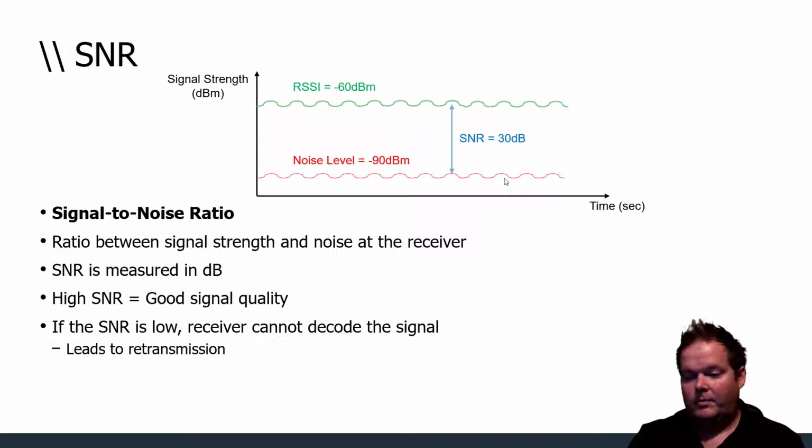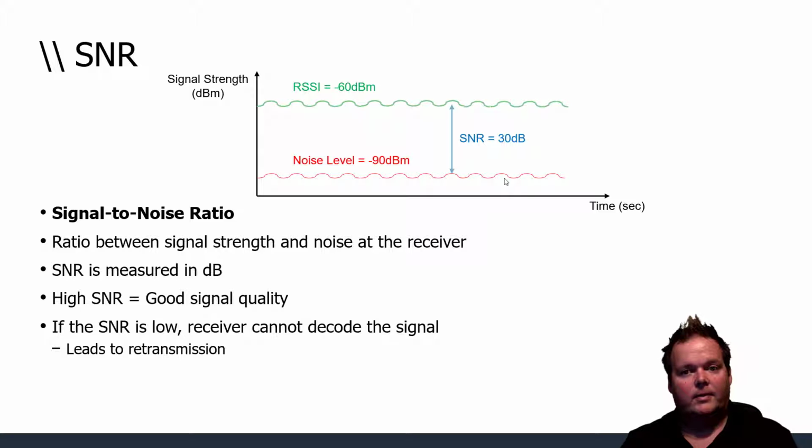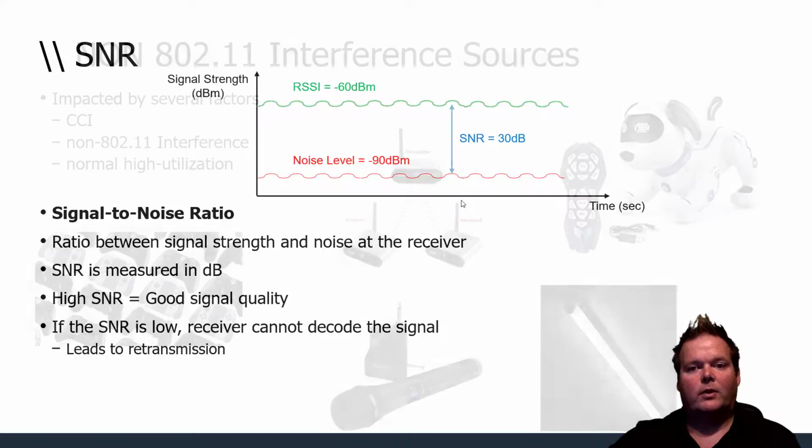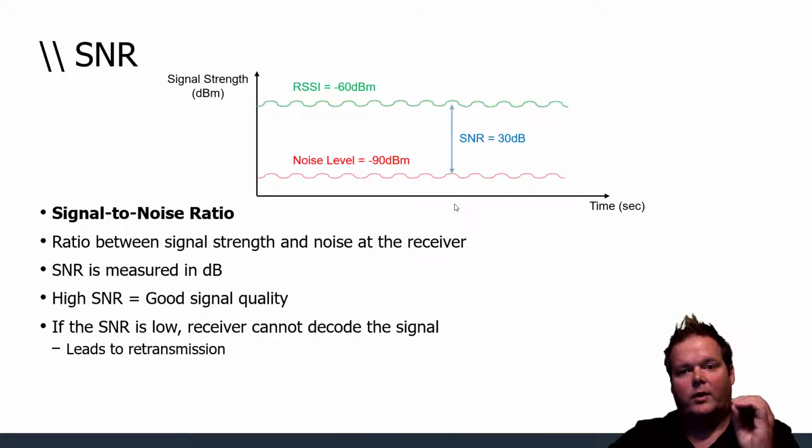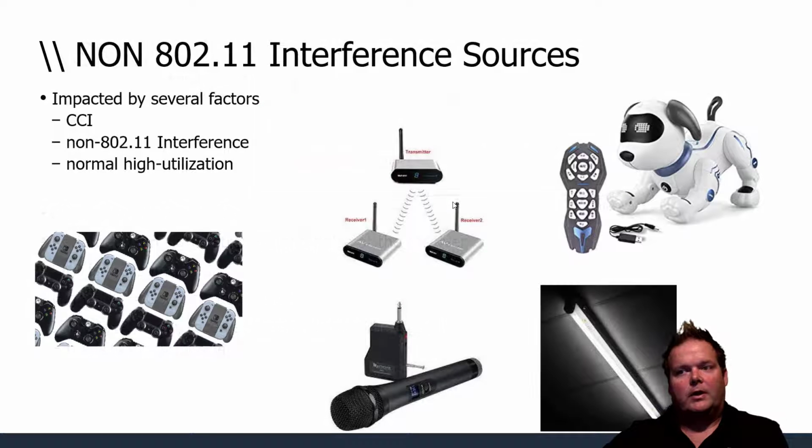So you might be going, hey, my channels actually have a good RSSI, or my clients are actually seeing a good RSSI, but the throughput is crap. What's going on, right? To dissect that, that's what we need spectrum analysis for: to dissect that layer 1 and figure out what is the culprit, what's going on. And there could be many things.